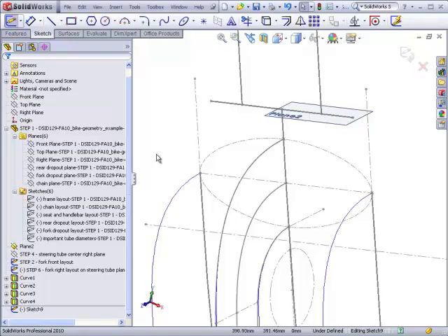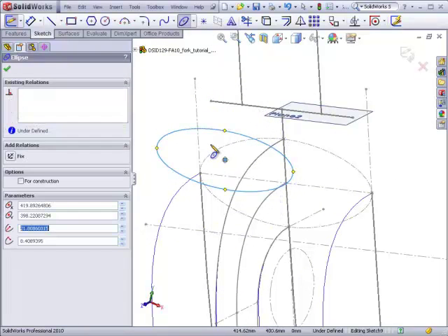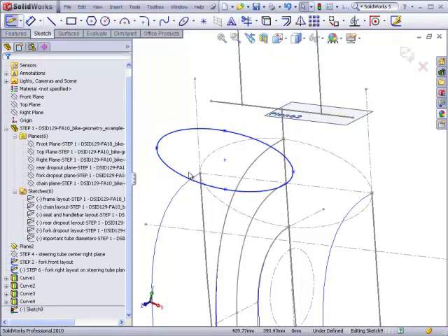So I'm going to do that, and instead of drawing an oval, I'm actually going to draw a spline. The reason for this is if I draw an oval, we have a little bit of a problem where ovals always require the major and minor axes to be at right angles to each other. We cannot guarantee that that condition can be met as the oval is being swept down these 4 guide curves, and as a result, the sweep might fail.